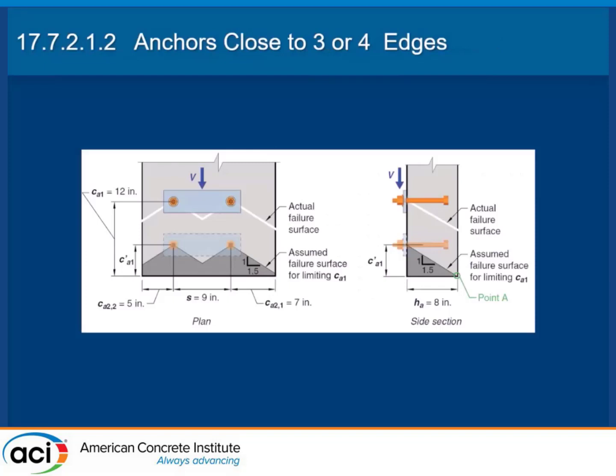Just like h effective, when we were in the top of that pier, even though your h effective might have been, say, 20 inches, due to the confines of the top of that pier it might actually only be 4 inches for your calculations. Same thing happens in shear.